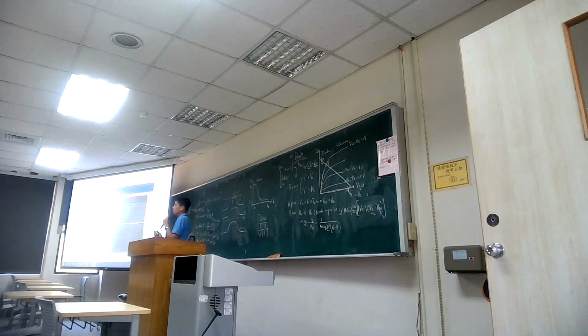But as I mentioned, there is a really good benefit: there's no leaking current from the gate side. You can also play with PSpice, place the current monitor at the gate side and see the corresponding current. Then you can see that after the triode region, the VG, the input voltage, the Vout, or the VDS is high.